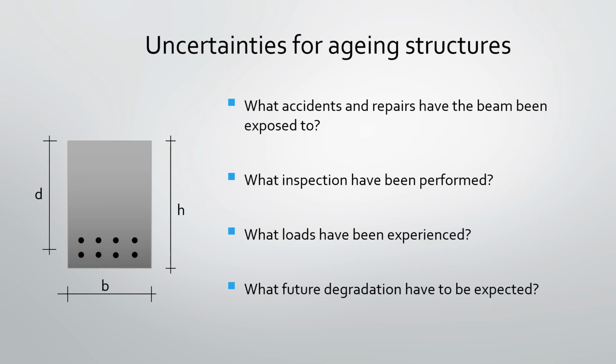If we have some historic data of the development of degradation so far, this can possibly be predicted with some confidence, but in many cases we will have little historic data, and the predictions will be very uncertain. In addition, the design formulae for the capacity may not be applicable for degraded beams. We may have to search for data from laboratory experiments, or perform our own experiments, and develop new analytical capacity formulae.